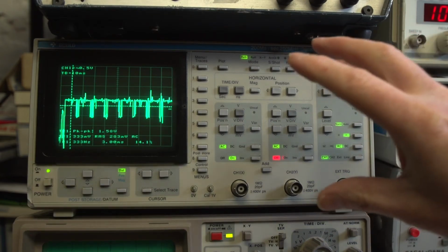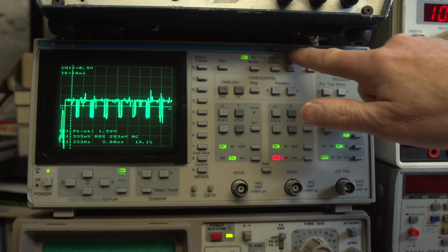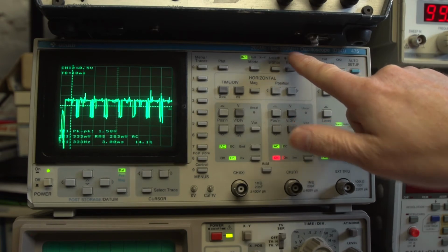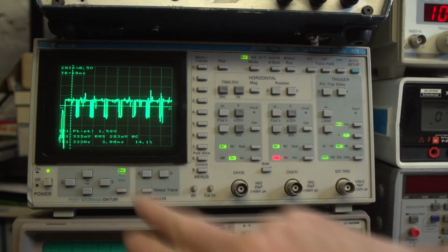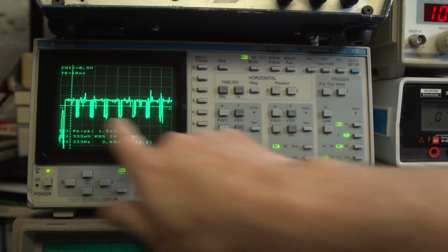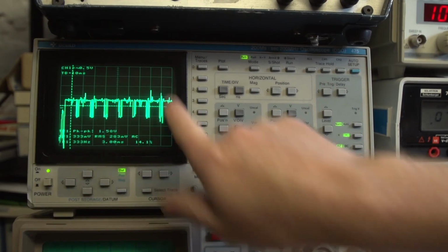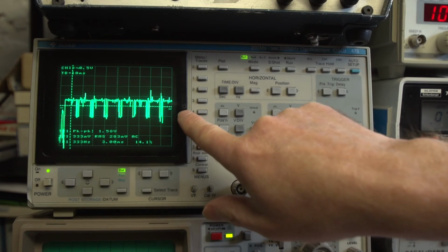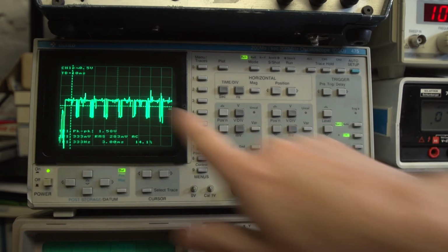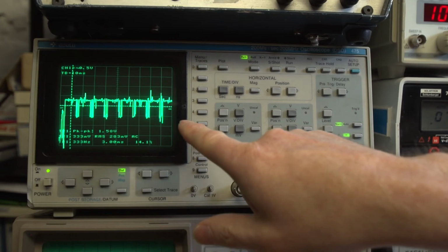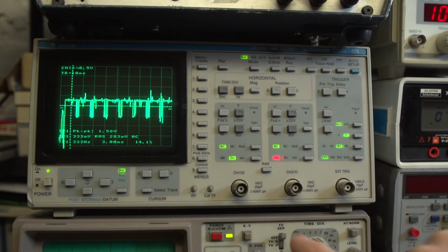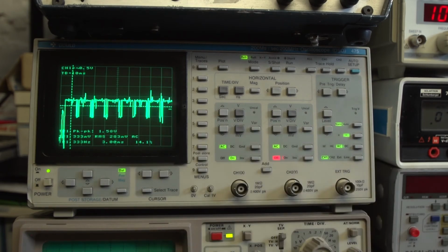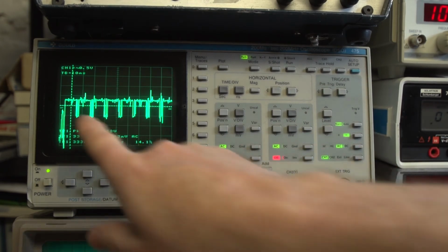The main advantage of this scope, as I say, is the input frequency bandwidth is very high. It's 200 megahertz, it's pretty good. But it is a storage scope, and as you can see, there's nothing plugged into the input yet. We appear to have a display here. This is something that was caught in the memory from, I don't know, weeks ago when I was doing something. And it's a snapshot of the actual waveform. So even though you've got the input disconnected, you can freeze the display and look at it at any time.